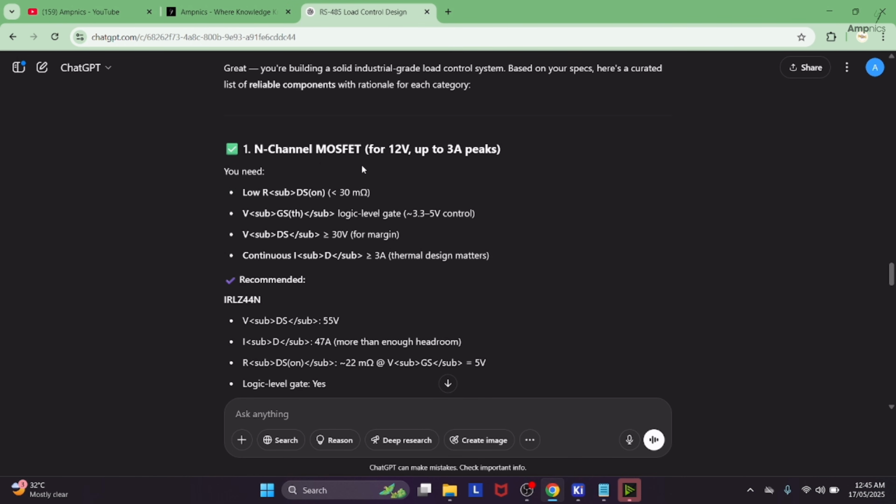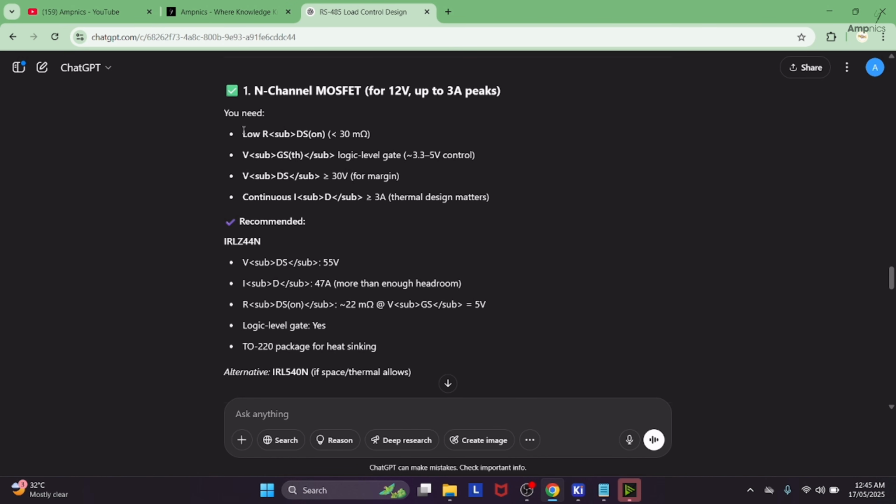So number one, N-channel MOSFET for 12 volt up to 3 ampere peak. So what you need, basically it is talking about every technical detail which is required for designing this project. I'm not gonna talk in detail. What I will do, I will share this chat in the description, you can read it by yourself also. But I'm interested in the selected devices. So it is saying that we can use IRLZ44N. Well, this MOSFET is an ideal choice for switching from 3.3 volts, so this is good, and we are going to use this device only.